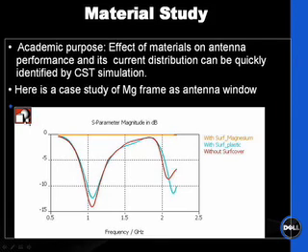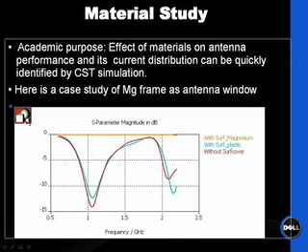Also, sometimes people want to make the magnesium frame and plastic as one piece, that is, you insert mold plastic in a magnesium frame, so it's just one piece. Then we were trying to see how much the magnesium frame is going to damage. Each property was studied: we put just a surf cover, that is just a cover, then a plastic molding, and then just magnesium, and looked at the VSWR. This way we can also use the simulation tool for academic study of the effect of each material. Here we have used this to make an insert molded plastic on a magnesium frame.